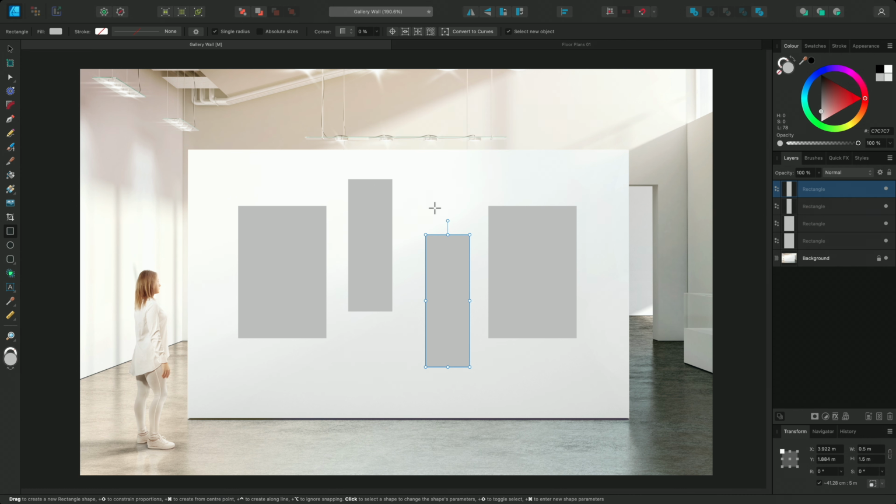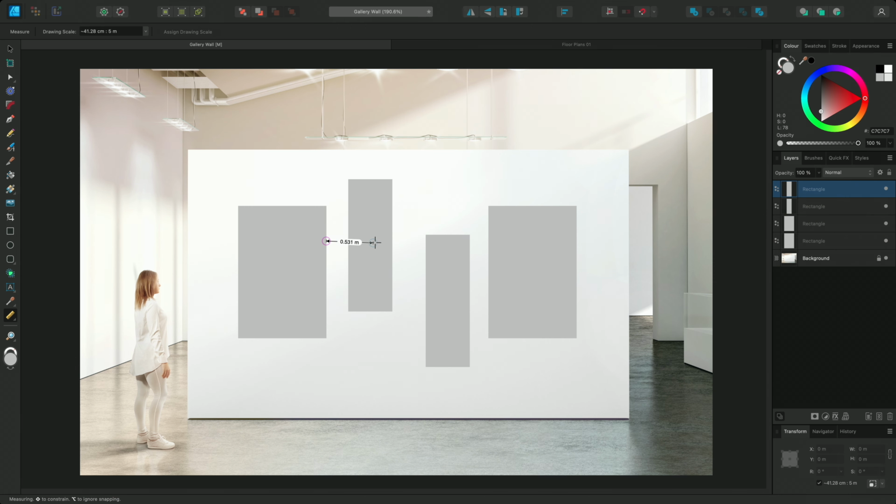Now there are a few keyboard shortcuts that may help you measure. As we saw before, Shift will lock the measurement to 45-degree increments. And if I pause whilst keeping Shift held down, a dashed projection line will appear, allowing me to make sure that my measurement is perfectly lined up. Additionally, I can use the up or down arrows to access this projection line for a vertical measure, or the left and right arrows for a horizontal measure.